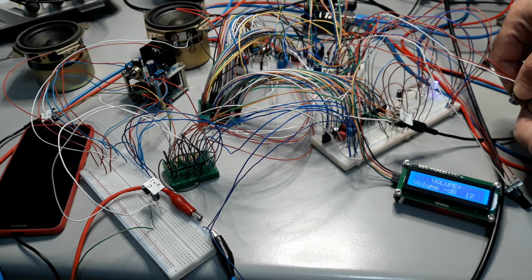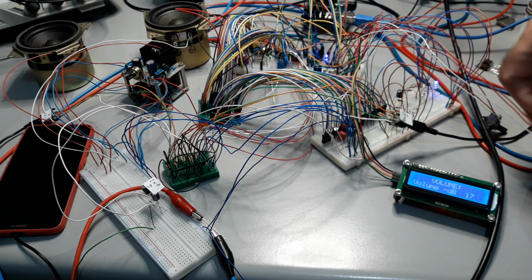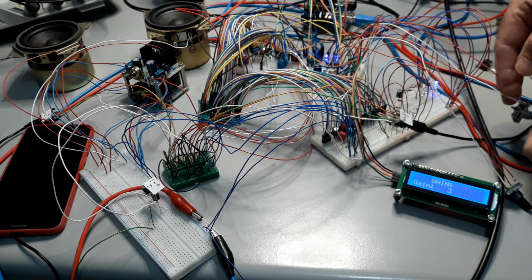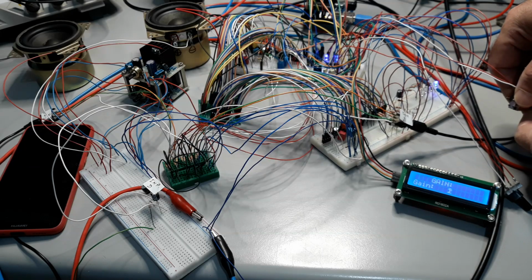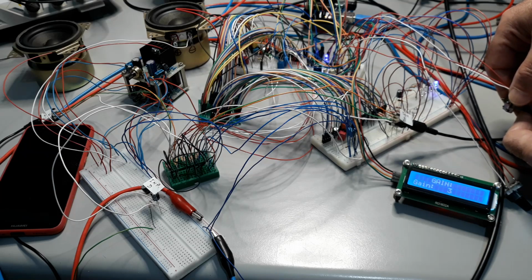At this point, it is important to be clear about one thing. This setup is not suitable for high-quality audio applications. Proper audio design would require coaxial cables for each audio signal, or a carefully designed printed circuit board layout to minimize electromagnetic interference. Those rules are clearly not being followed here. This project is strictly a functional test and a proof of concept.